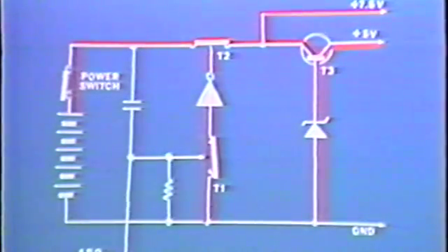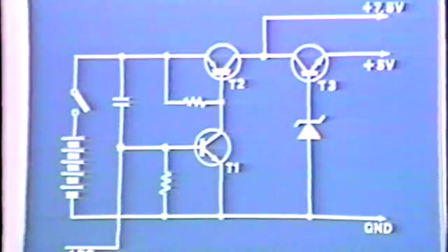To conserve the batteries of the Casio tone, an automatic power-off APO function is provided to automatically turn off the power when a key is not pressed for a certain length of time. This operation is controlled by the signal APO from the CPU. When the APO signal is low, this turns off T1 and T2 and stops the plus 7.5 volt and plus 5 volt power supplies. Have you noticed anything about what has been explained so far?